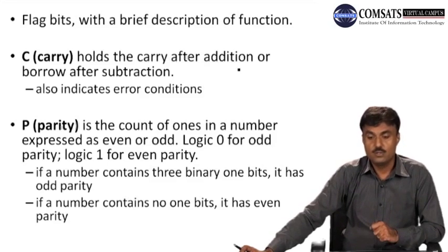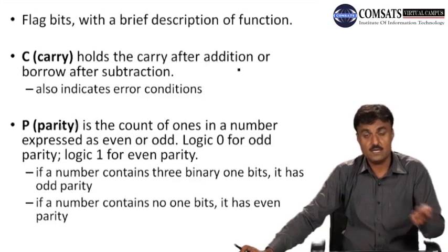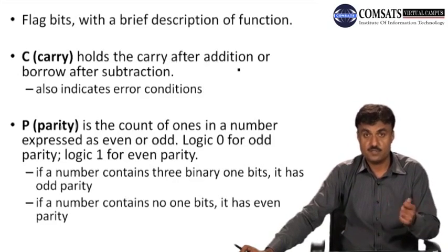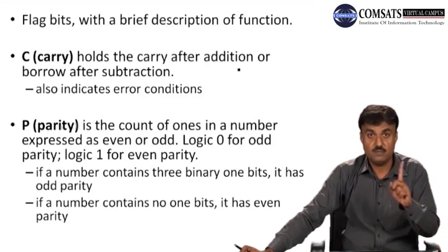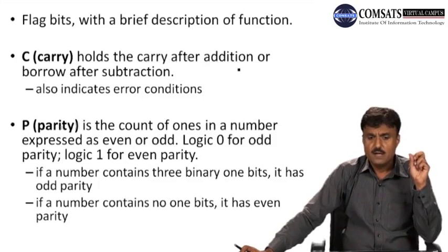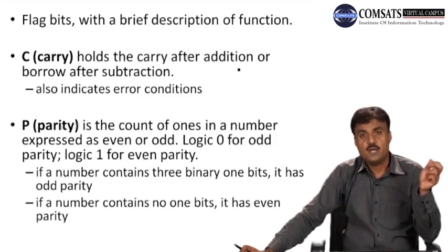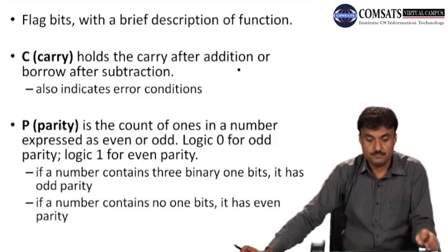This carry holds after addition or borrow from subtraction. So this, if it is 1, means there was a carry inside the arithmetic operation, or if we borrow in subtraction, this bit will be 1. Now if there was no carry involved, then this bit will be 0.